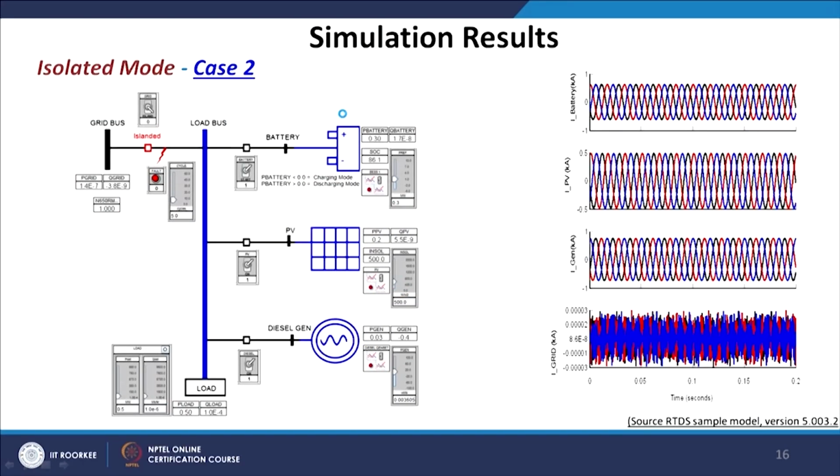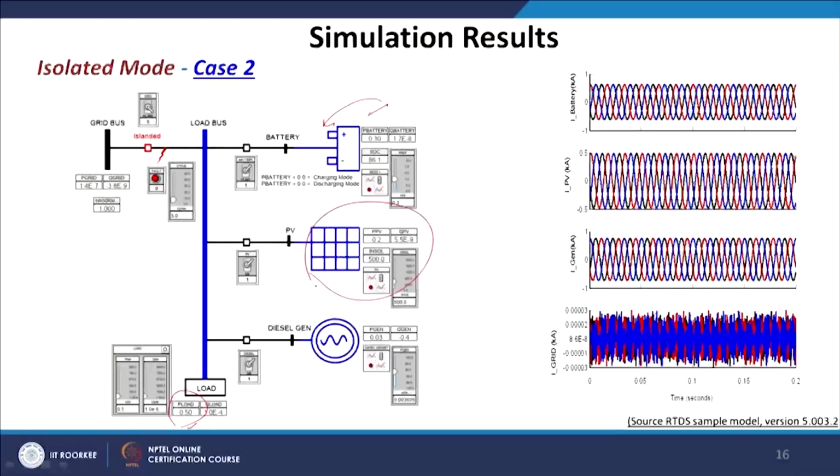where you allow your battery to discharge instead of charging, and the same load is being maintained. So, if you take 0.3 from the battery, then we need an extra 0.2 because the load is 0.5 and the battery is now giving me 0.3. So, I am short by 0.2 units, and that 0.2 unit can come from my PV, which is not operating at its MPPT.